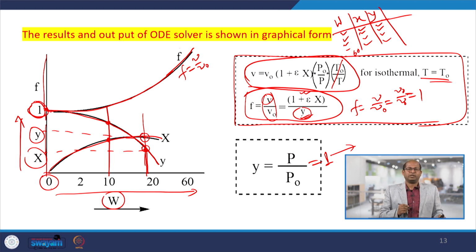Inside the reactor, we are taking ethylene as a reactant and oxygen or air as a reactant, giving ethylene oxide for this particular reaction. If we solve these two equations, then the nature of the catalyst weight, conversion, pressure, fractional volume change or volumetric flow rate change inside the reactor, we can easily predict or calculate based on the data available. So, this is the way we can solve any numerical problem.